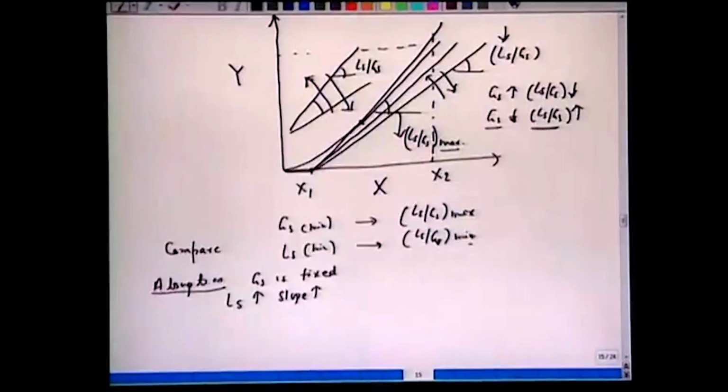If the slope increases, then the driving force delta y increases, height decreases because now we have large driving force. So we require a smaller height to achieve these concentrations, and look at this movement of x mole fractions. If we increase the slope from here to here to here, the concentration of x will move in this direction, or the spent liquor will be dilute or will have small concentrations.